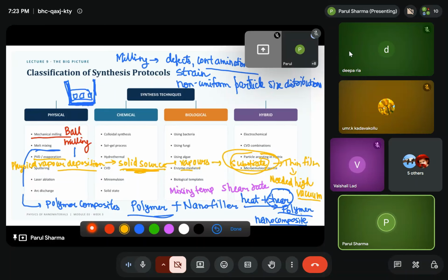Under vacuum, fewer collisions will happen and there is a longer mean free path. Therefore the vapor particles can travel more directly towards the substrate. So lambda, the mean free path, is related to pressure: reducing the pressure will increase the distance a particle can travel before colliding.